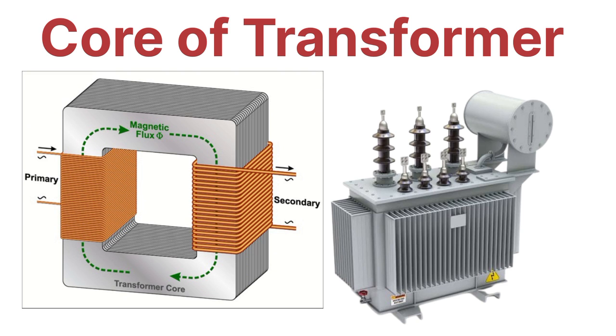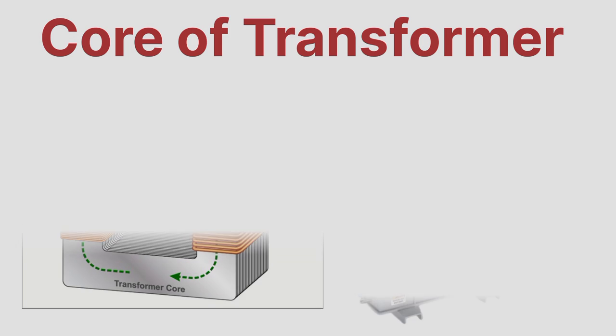By placing the primary winding at the core, it will create the magnetic field and also flow the electricity through the core. As the magnetic field cuts through the secondary winding, the secondary winding picks up the voltage. Then the power is stepped up or stepped down in relation to the number of turns of each winding.